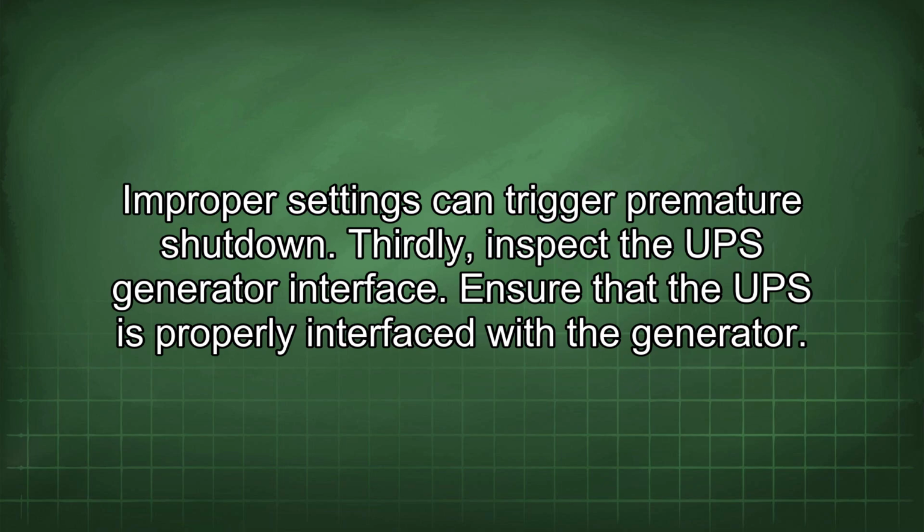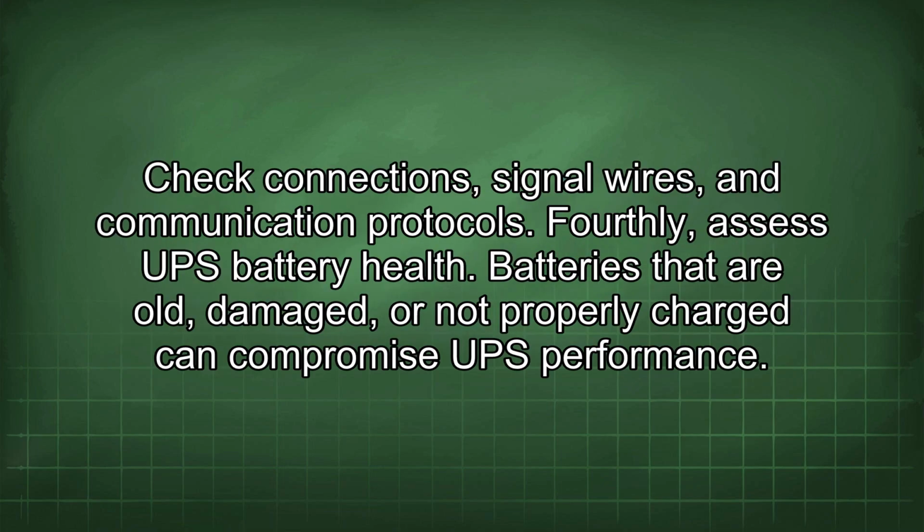Thirdly, inspect the UPS generator interface. Ensure that the UPS is properly interfaced with the generator. Check connections, signal wires, and communication protocols.